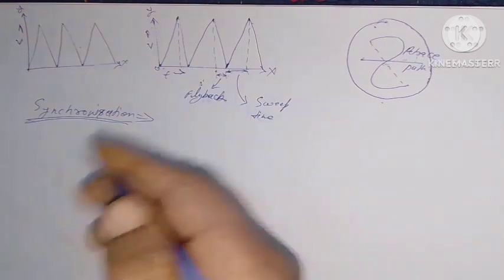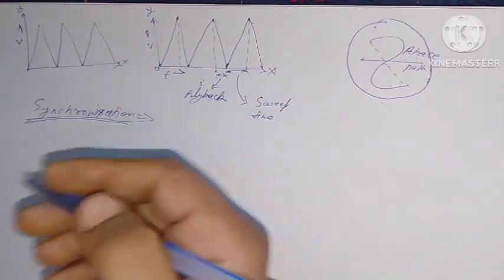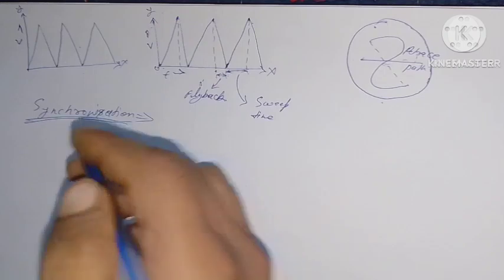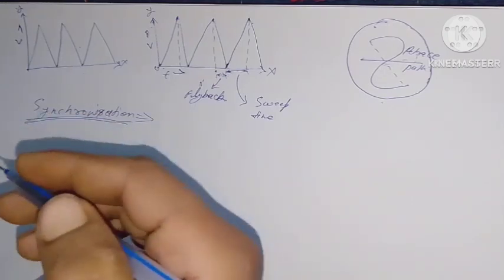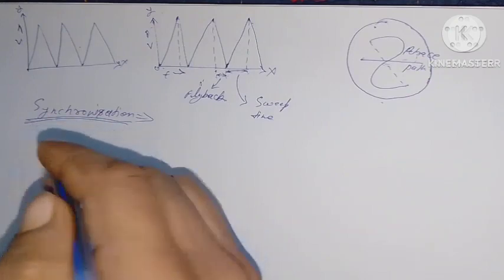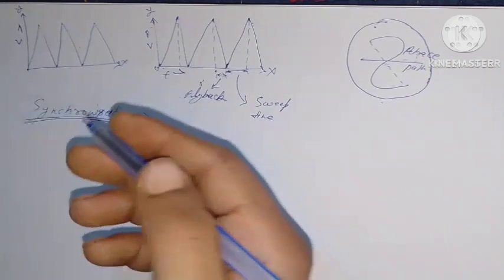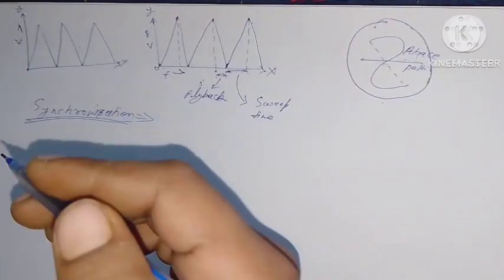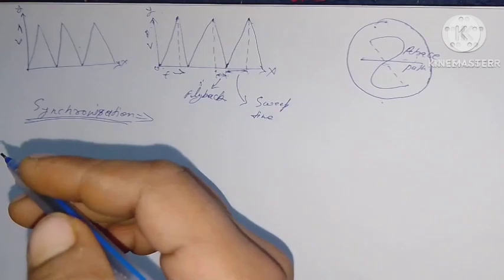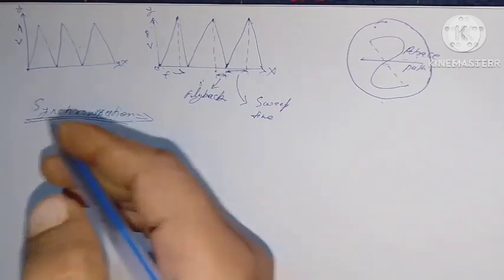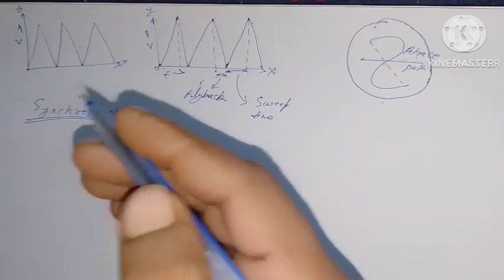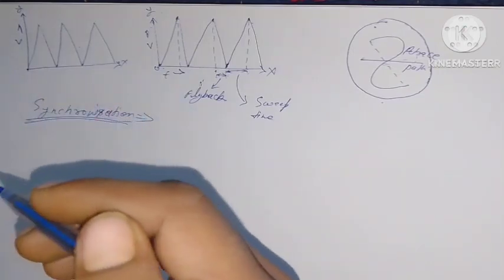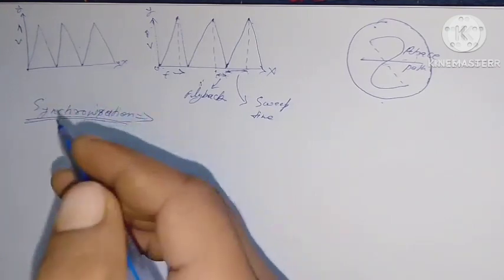Okay, when two events occur simultaneously, they are said to be synchronized. The input signal applied to the Y plate is synchronized with the sweep signal and will appear stationary when the beginning of a pulse of the signal wave train is caused to appear at the beginning of the sweep trace.